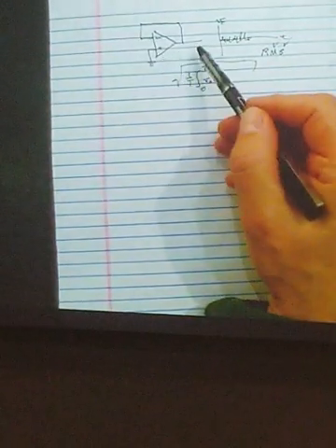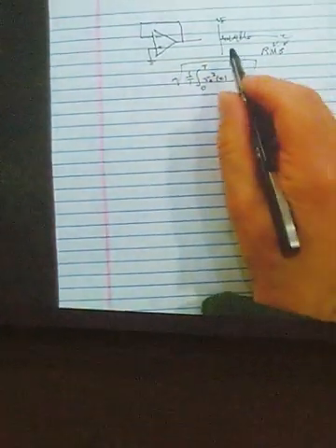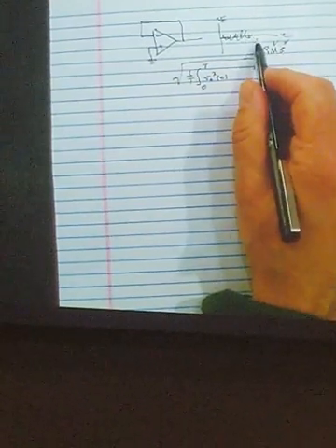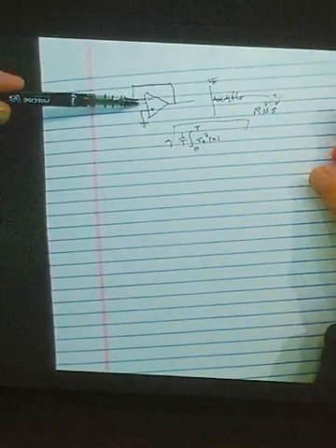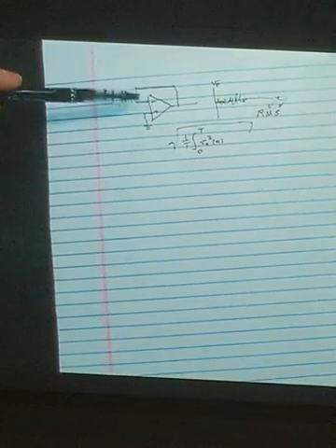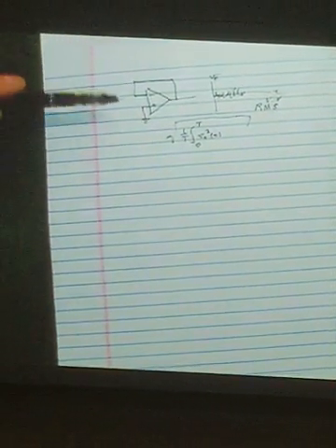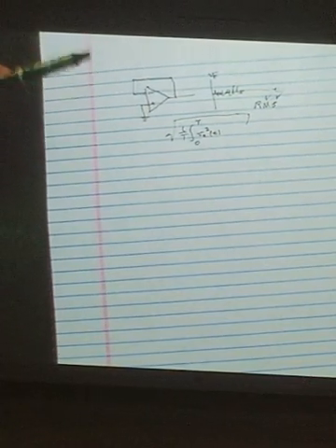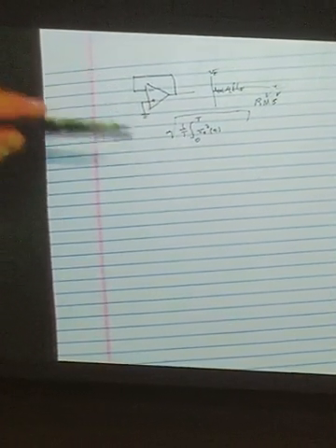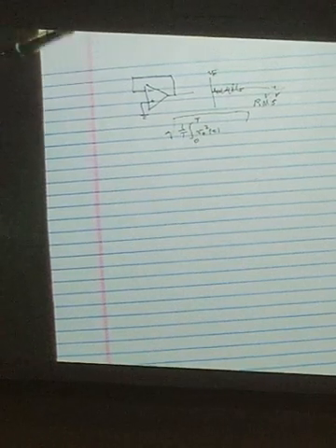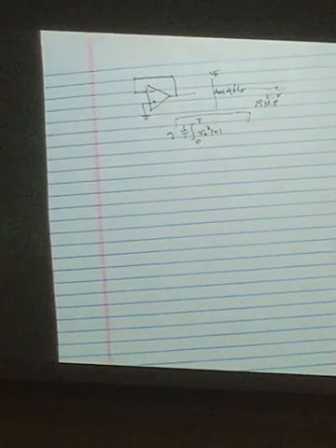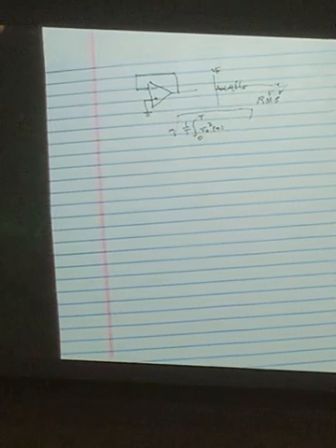So we usually like to think of these random signals as their RMS voltage, because we can't predict anything about this signal. It's a completely random noise signal, and it's due to various random fluctuations in the components inside the op amp. Now you can have other sources of noise. You can have 60 hertz noise on your power supply bleeding onto this, or things like that. That's not what we're talking about here. We're not talking about those kind of coherent signals.